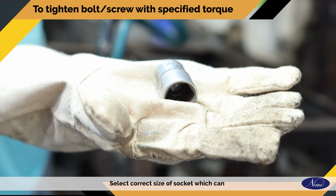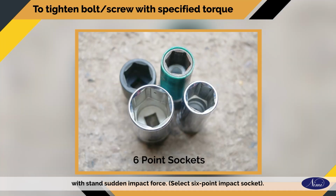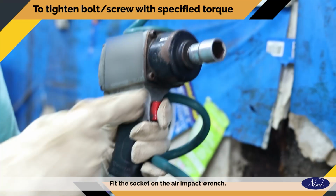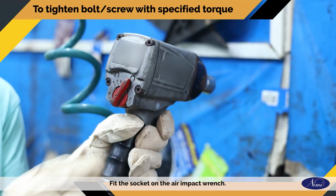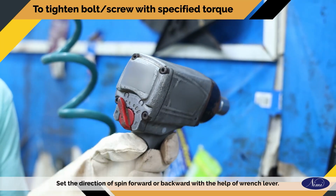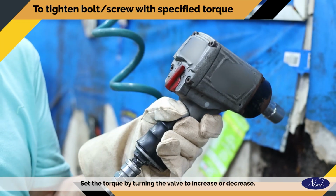Select correct size of socket which can withstand sudden impact force. Select 6-point impact socket. Fit the socket on the air impact wrench. Set the direction of spin forward or backward with the help of wrench lever. Set the torque by turning the valve to increase or decrease.